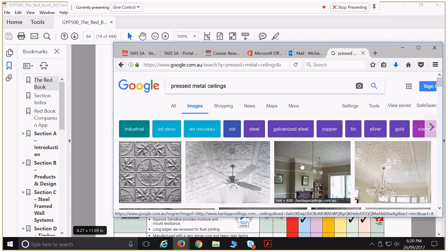The poles will take up moisture from the mud and expand while the mud contracts, and those walls actually stay relatively well sealed because they regulate each other's moisture. Following on from that, there was the technology developed in Europe whereby you would have timber frames for buildings, and then you nail small pieces of timber between the upright members of the frame, and then you put a cementitious render on them.